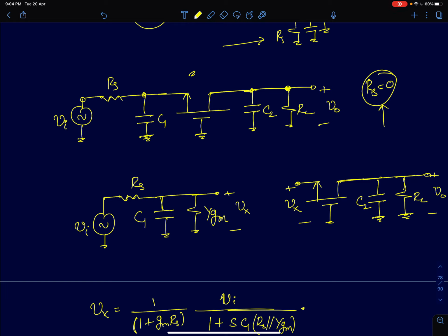And we said in specific cases, it does still find its applications in radio frequency circuits where the input impedance need not be very high. The input impedance usually is matched to some few tens of ohms. In such cases, common gate amplifiers find their applications. So keeping this in mind, we will analyze common gate amplifiers and look at all the important parameters of it and how they change as a function of frequency.